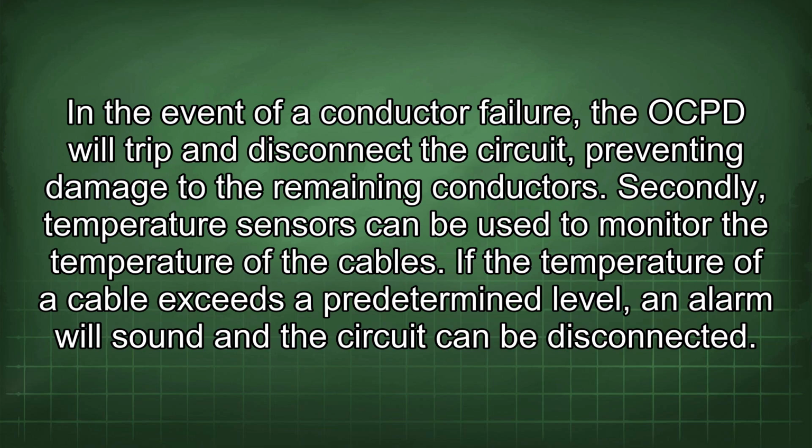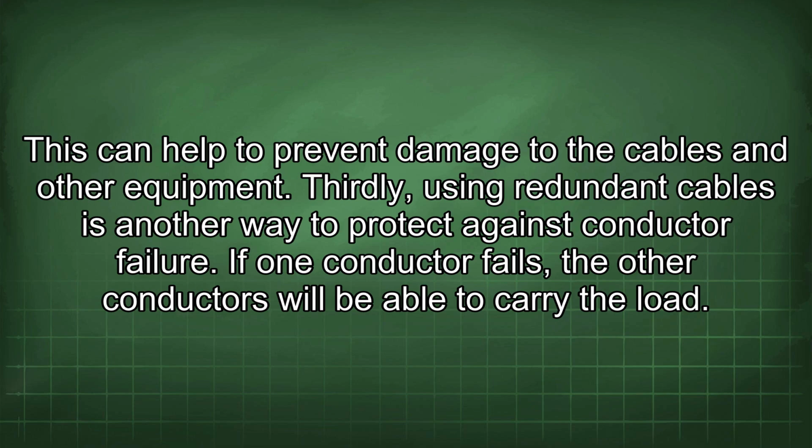Secondly, temperature sensors can be used to monitor the temperature of the cables. If the temperature of a cable exceeds a predetermined level, an alarm will sound and the circuit can be disconnected. This can help to prevent damage to the cables and other equipment.